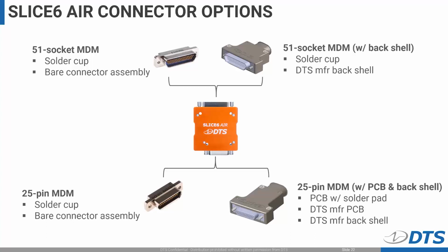The system side is a little bit unique in the sense that we'll also be offering a custom PCB with solder landing pads. So instead of having to wire leads to solder cups, it's going to be much easier to do that with the PCB. The reason is that if you're chaining multiple modules, both the power and the Ethernet lines would need to be bused. It's going to be a lot more difficult to cram 2 or 3 wires into a single solder cup than it would be to just use solder pads.